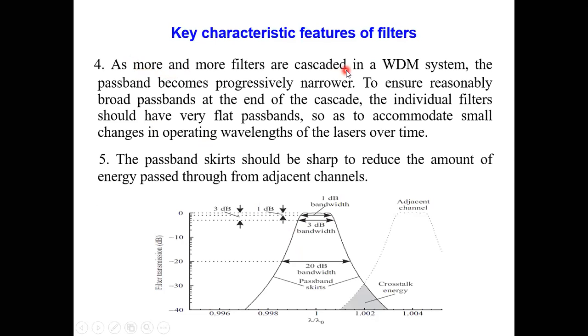Now see, we have a WDM system, that is wavelength division multiplex system. We have many wavelengths. We have been telling that a single fiber can carry multiple thousands of signals. Those thousands of signals will be centered around, we are not using the first optical window, we are using the 1310 and 1550 nanometer optical window.